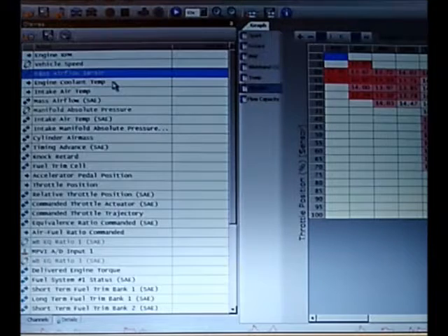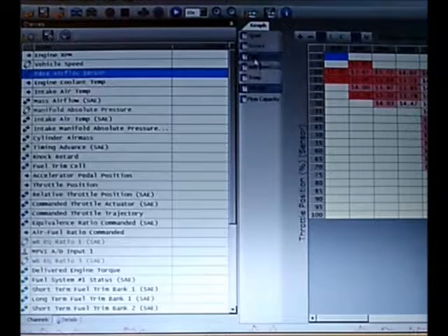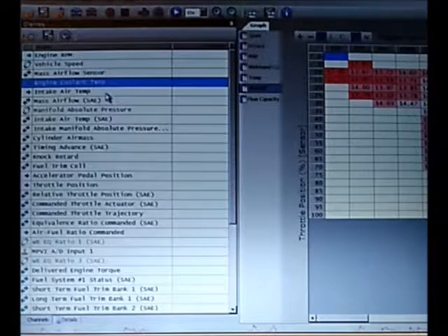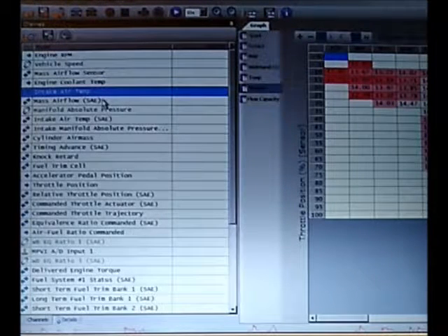Mass airflow sensor, not totally necessary for an open loop tune, but I would put it in there anyway, so that all the tables work and you have some additional reference that will help you understand your car and how it's behaving. Engine coolant temperature, you always need that. That's important to have. Intake air temperature sensor, again, you need that, and I think it's one of the PIDs we're logging, so yes.